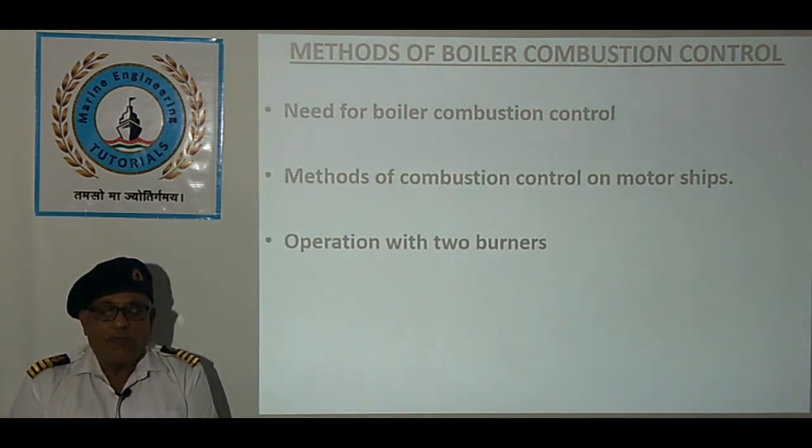To keep the boiler firing continuously, two burners may be used in which low capacity burner fires continuously, high capacity burner can start at lower setting and stop at control point, thereby maintaining steam pressure between two specified limits.